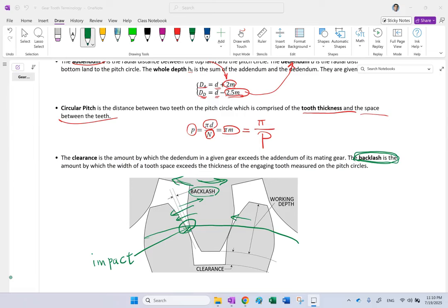So they're going to enlarge, expand, and when they expand, then this gap will be filled, and that is when you see the gear system start to jam. So you need some bare minimum backlash to avoid the thermal expansion jamming of the system, and to minimize that, you always need to lubricate the system and make it cool down and not thermally expand so much.